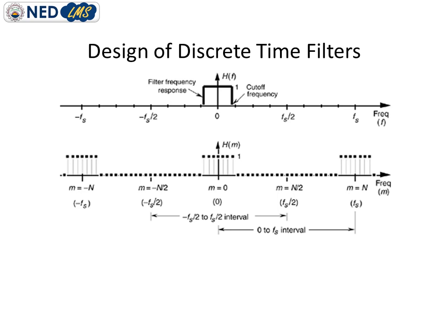Here you can see I am highlighting in this slide that this is a rectangular pulse, if you notice it from m equal to 0 to Fs by 2. And we already know that the transform pair of a rectangular pulse is a sinc function.